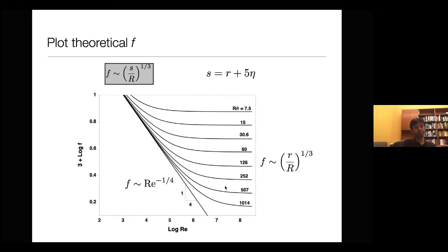And what you immediately see is that, well, of course, by construction, we get the asymptotics right, but none of the interesting features, specifically bellies and the hump that we saw in Nikuradse's data, are evident here. In fact, here, there's a monotonic transition from one regime, the Blasius, to the Strickler regime. So it may well be that the theory or this model is so simple that it is incapable of capturing it. Or it may be that the model is missing something rather crucial, but if we add that, we'll be able to start to make sense of the other things. Well, it's the latter, and I'll show you how.